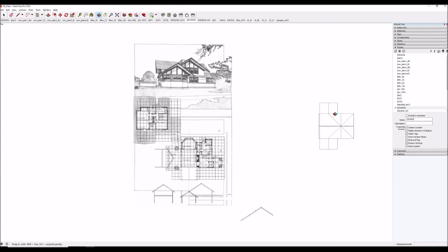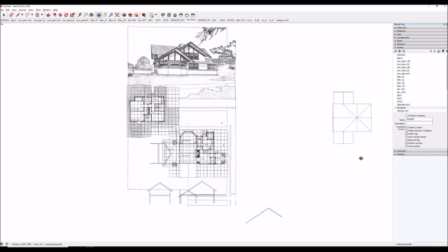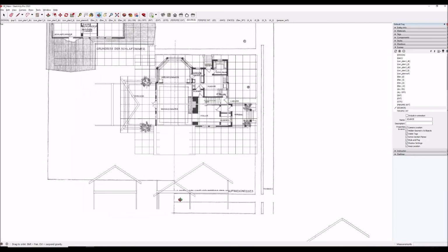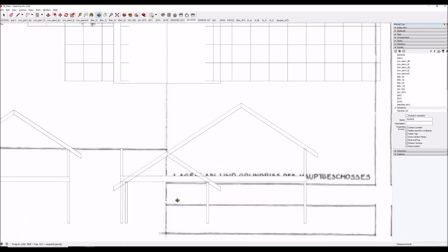So I drew out the roof geometry in a flat plan view. That's over here on the right. And then I also did a little rough section study. What I have is the ground level, the first floor. I have 9 foot 1 inch wall plates, wall heights for the first floor. I have a floor plate. And then I have a second floor roof that starts at the top of this wall, which I estimated, a preliminary estimate, at 6 feet. It comes up and it comes back down and lands on top of the ground first floor walls.